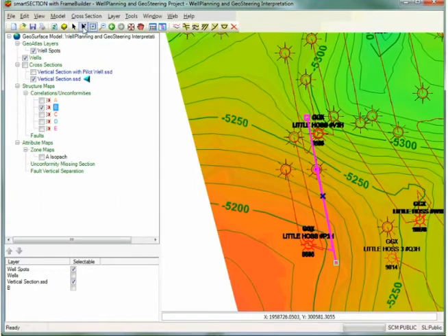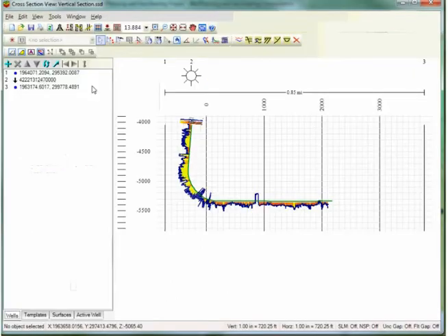The vertical section cross-section shown here is laid out along the horizontal reach of the well being drilled. The drilling well is projected orthogonally into the plane of the projected cross-section. The point of intersection becomes the zero vertical section origin for measuring horizontal distance from the well position. Engineers call this kind of projected cross-section a vertical section.